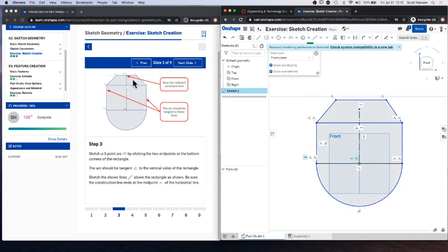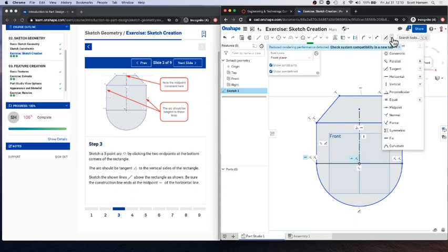So I do want to go through and make sure I've got some consistent geometry constraints here. This top line is horizontal. I can see that little horizontal line telling me. But you'll see that this line here is not attached to the endpoint of my vertical line. And so, I can try to click, move, and drag it over that line. I could try undoing and drawing this line again so it goes through that point. So that point's highlighted.